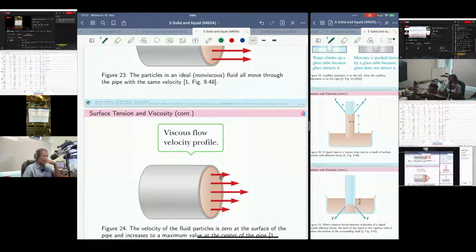there is a friction, as you know. First, there is a friction between the liquid and the solid material here. There will be friction between the fluid and that solid, and that will cause obstruction, and the fluid close to the surface inside the pipe is going to have lower velocity.